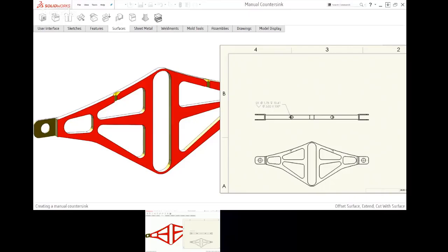If you really want to model just a pair of cables, you pick a baseline, go to a cylindrical or circular surface sweep, then you do the same helical line with the intersection curve, and you get the same thing. And then you can sweep it along. Yeah, it's exactly the same workflow. Yeah, sounds like it. Certainly one of those features.